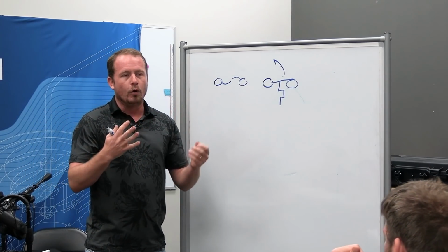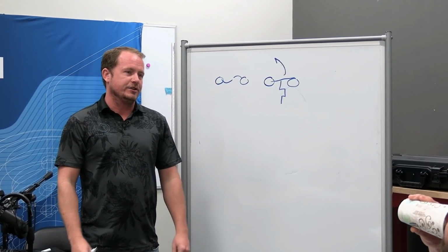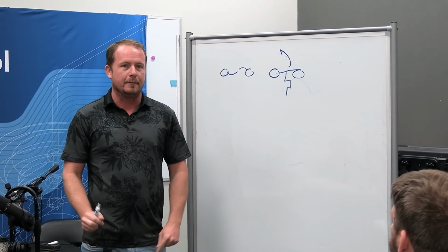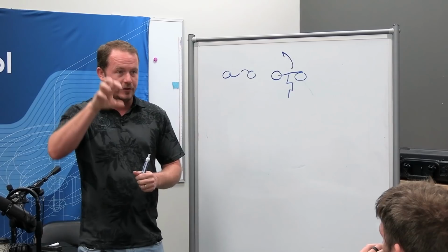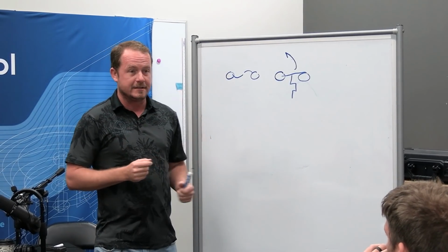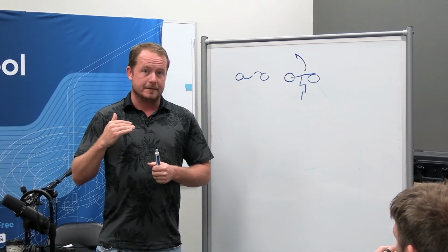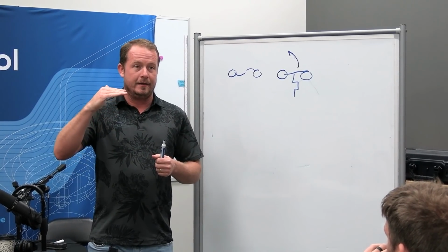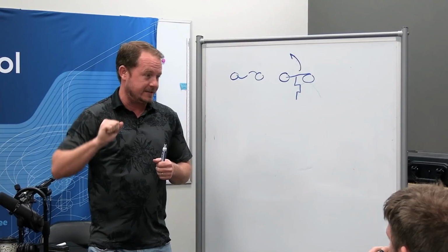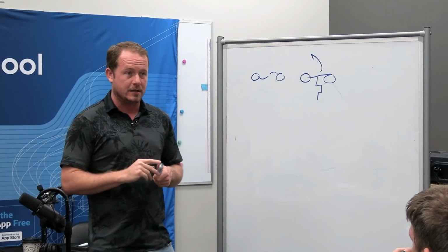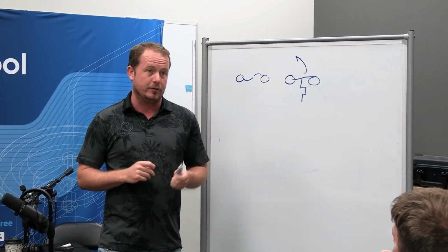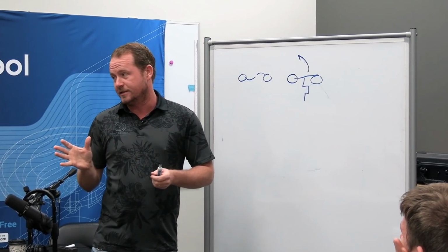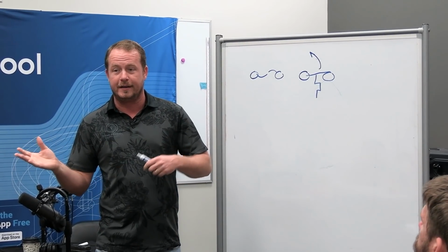So in an old fuse box from a generation ago when they didn't have circuit breakers, every time a fuse would blow, you would have to go out to your circuit panel and replace the fuse. Nowadays, it's like this. When that breaker overheats or has a magnetic overload, either way, it opens the circuit and then you have to reset it, right? But it's all the same philosophy. In most cases, circuit breakers are thermal, meaning they actually trip when they get too hot, which is why, coincidentally, you get more trips in circuit breakers on really hot days than on cooler days.